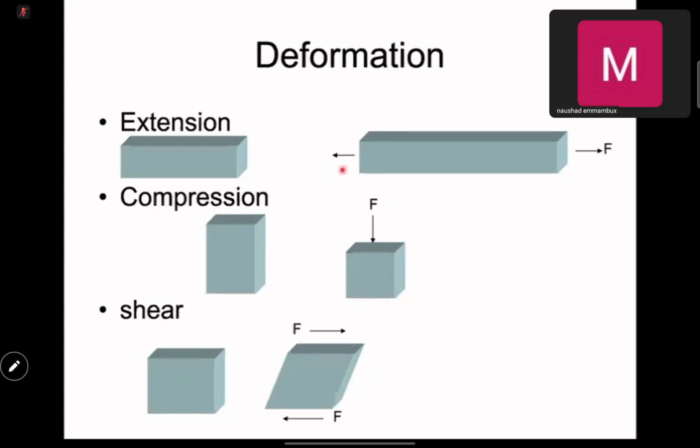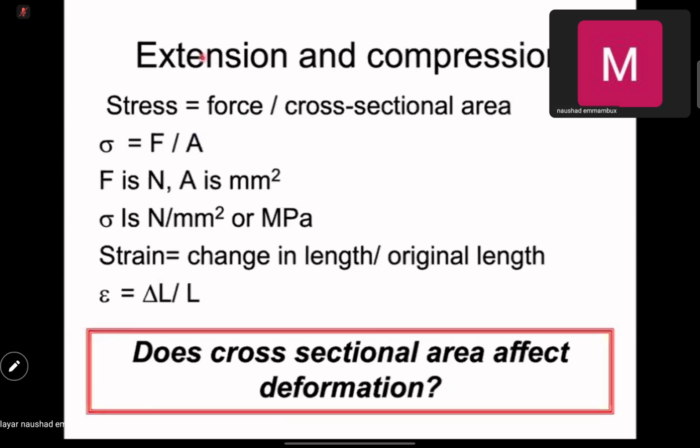Okay, and to compare results in a texture analyzer, if you're doing extension and compression, you need to have the same size, more or less. Because if you extend or compress something, the bigger it is, the more force you will need. But in rheology, there is a way to normalize this. So you change the extension and compression force, which you get in Newton, and make it in terms of stress.